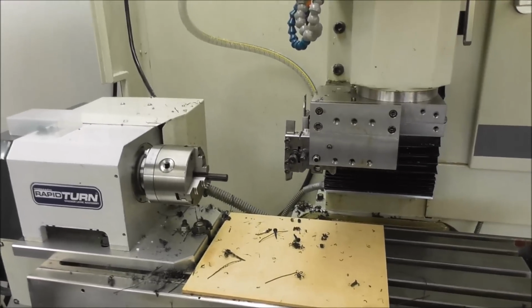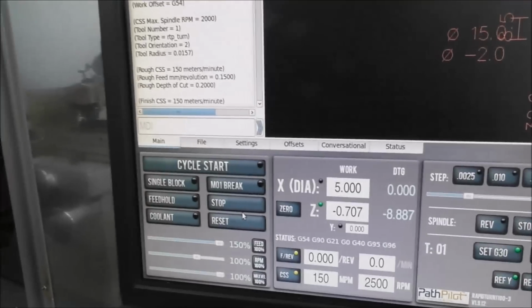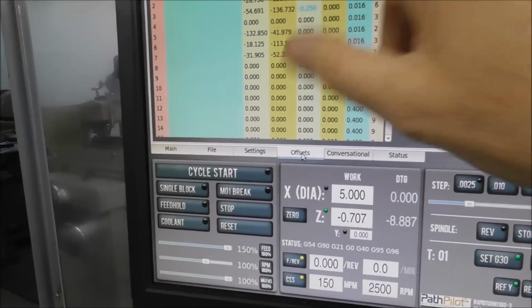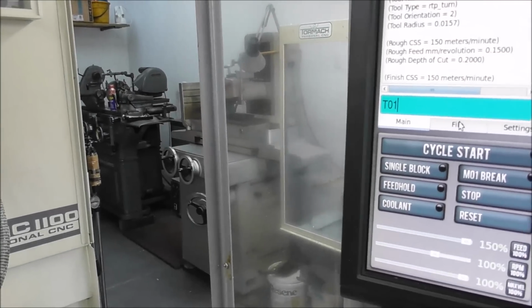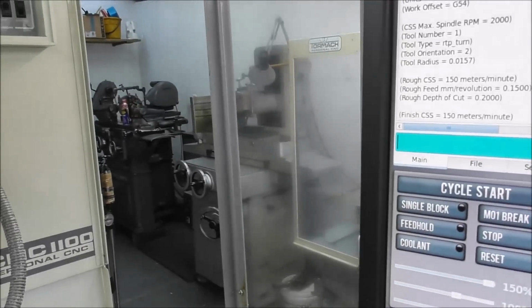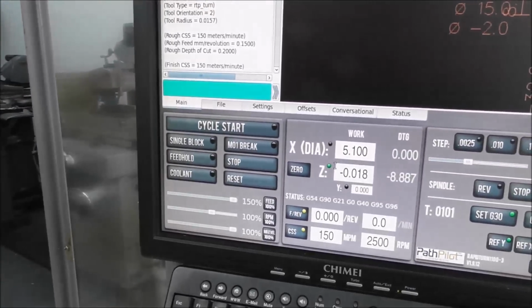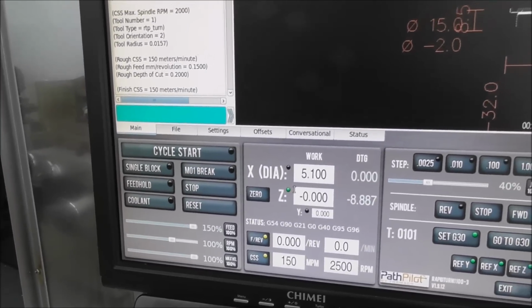And you can see we're running the program there in fresh air, and the other tools will all be linked to that relative position because we changed the main DRO and not the offsets in the tool table here. That all remains the same, they're linked the same. So what we can do now then is go back to that T0101. We've got back to that. We can wind back to that position we were in, that we had entered 0 on, find that 0, and enter the number that was in there, and we got the tool back to where it was.